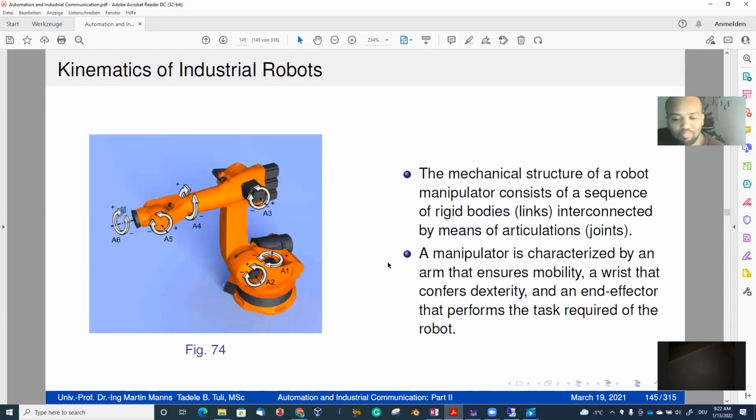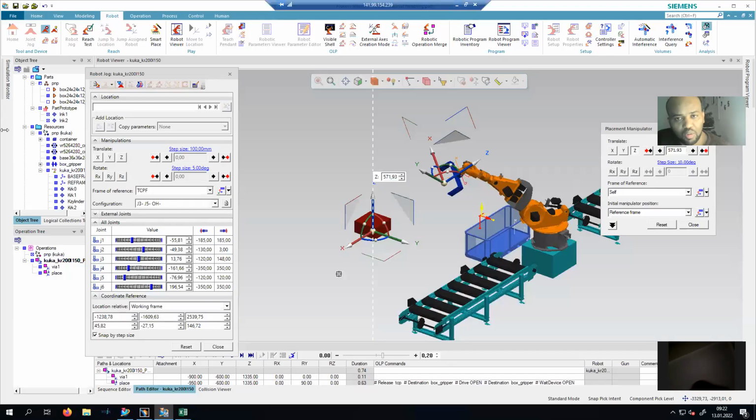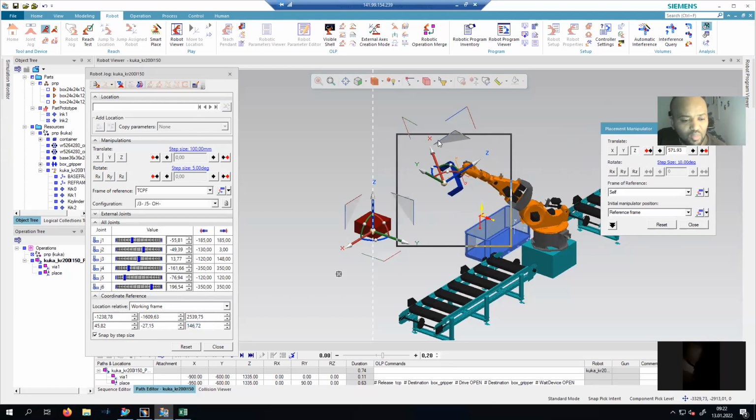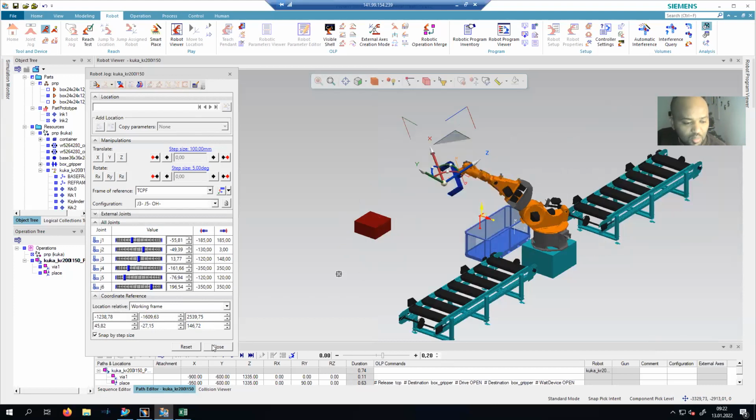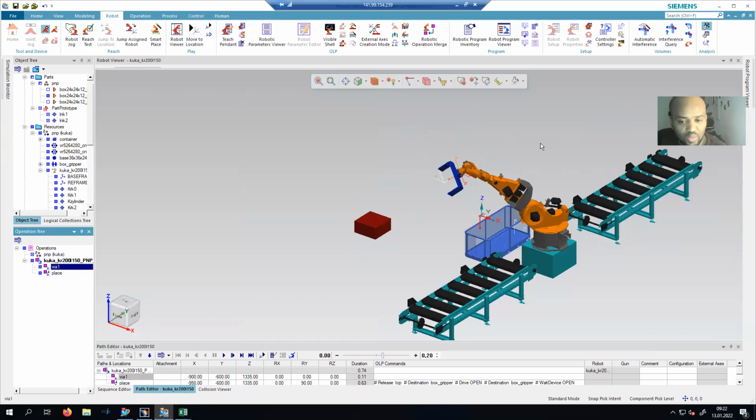Okay, if you get 4 by 4, then life is easier, because you can manipulate your transformation matrix from one to the other. So accordingly, from the simulation environment, we have positions X, Y, Z, and rotation about X, Y, Z, and these are all represented in a working frame here. This working frame is a 4 by 4 matrix, and this 4 by 4 matrix will let you calculate the points from via1 to via2.